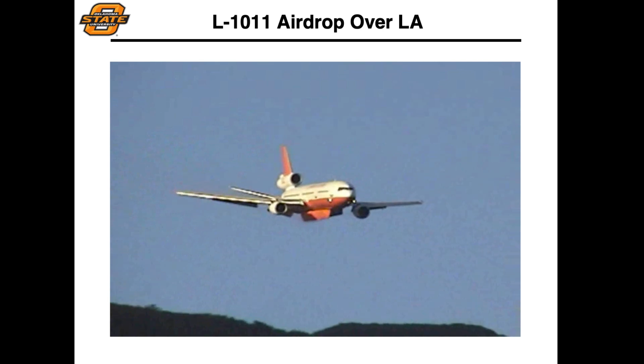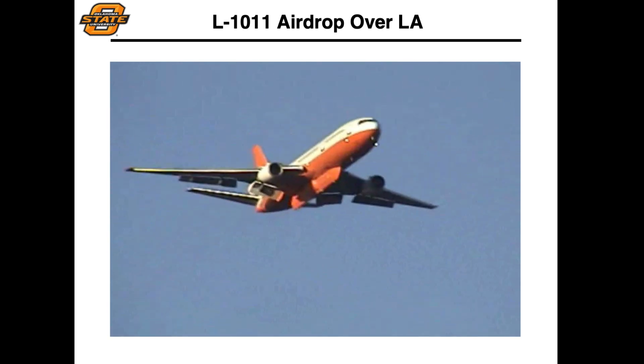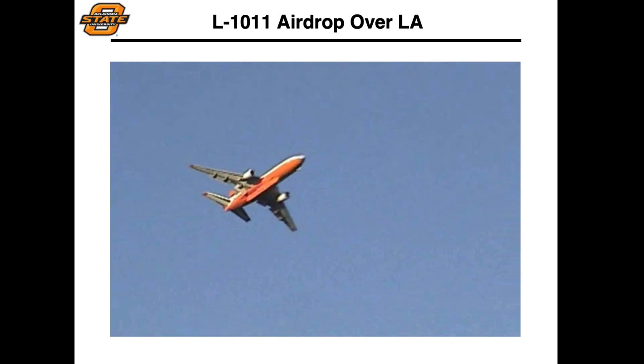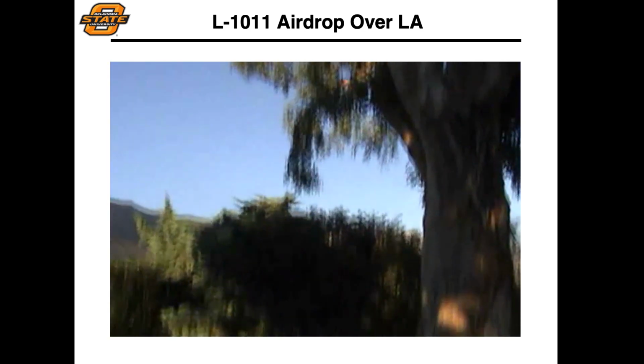And again, ostensibly, the nominal condition here is that the lift is going to be approximately equal to the weight of the aircraft. If you're deploying a massive amount of load, in this case a significant fraction of the overall maximum weight of the aircraft, you have to be changing the lift at the same time that you're deploying this load. So think about what the wings are undergoing as it performs this payload drop and simultaneous maneuver.